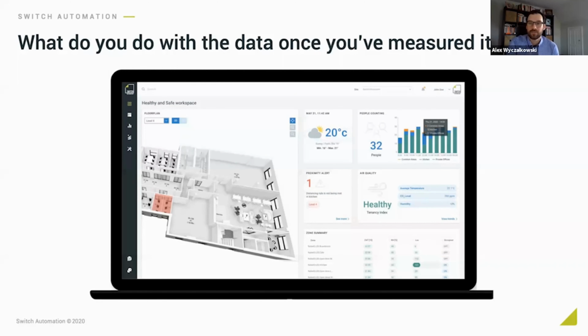Maybe you thought you could have 50 people in your building. Maybe after looking at the data, you said, hey, we can't get CO2 where we want it to be with 50 people. So we've got to limit it to 30 people if you've got a retail space, something like that. So again, using data helps drive decisions, and in the end, in this case, to keep people safe.